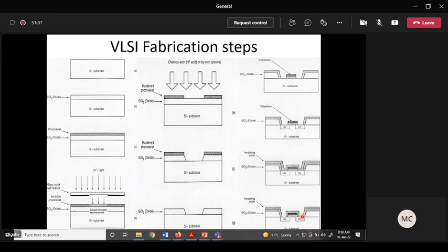So you do the fabrication layer by layer. When you are making the source and drain, you make them in all the MOSFETs present in your chip in one go. When you are depositing oxide, you are depositing oxide on the whole wafer. That way it is automated and reduces cost. You are not making individual MOSFETs; you are making layer by layer, and the same layer you are depositing all over the wafer depending on where you need it. That is why it is called batch fabricated, because you are doing things in batches and making devices in millions or billions on the wafer.